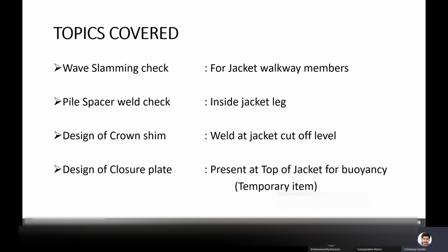Then it is the pile spacer weld check. We know that, whether it is grouted or ungrouted, there will be a pile spacer inside the jacket leg, and a pile will be inserted in the jacket leg. So there will be a spacer there. At each and every framing level, the pile spacer will be provided.